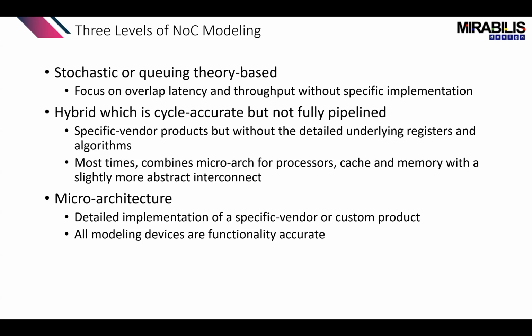Microarchitecture plays a key role when you're trying to actually implement a particular component as opposed to trying to reuse a third-party vendor product. This becomes very important because not 100% of your chip is going to be a third-party vendor. Some of it is going to be part of your custom design. And also, you might use this operation to fine-tune your vendor specification by modifying some of the constraints or some of the attributes that are associated with it. So microarchitecture plays a dual role there.